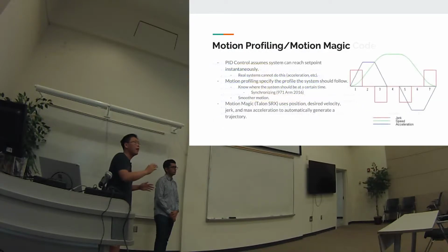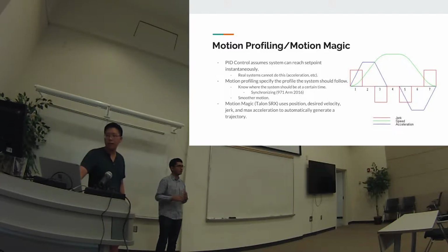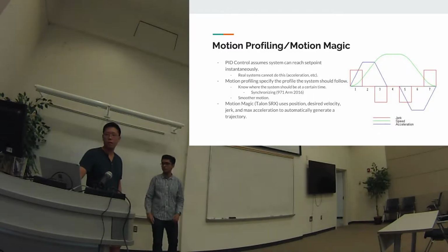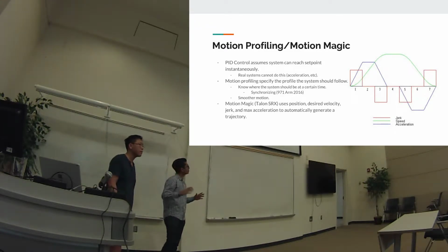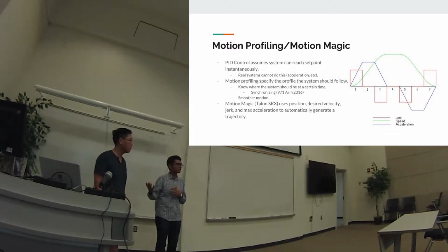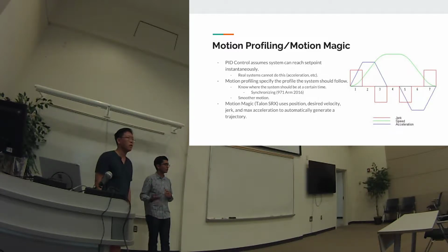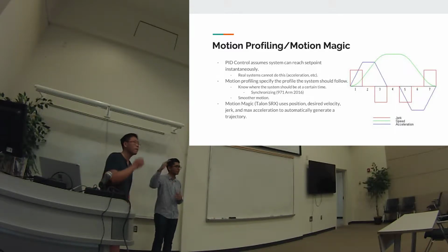How would you determine max acceleration? So yeah, we tune that along with when we tune our elevator, for example. If you go back to the example, you can see how when our elevator moves up, it speeds up and slows down, right? So what's really happening there is our max acceleration. When we're mechanically designing our robot, we know how fast the elevator can move and how fast the drivetrain can move. Say, the benchmarks as you're going? Yeah, exactly. And then our cruise velocity is where our optimum speed would be, basically like an average of where we'd want to go.